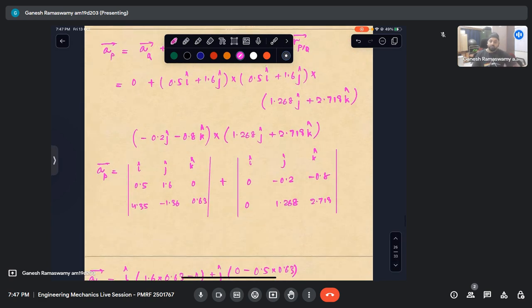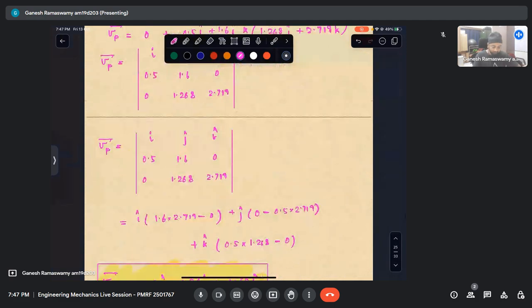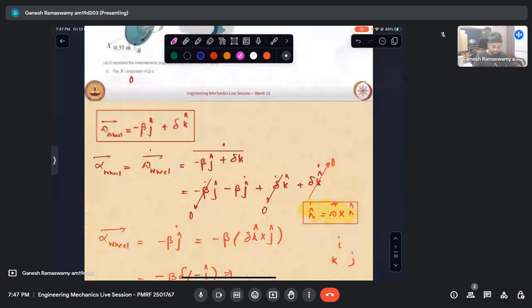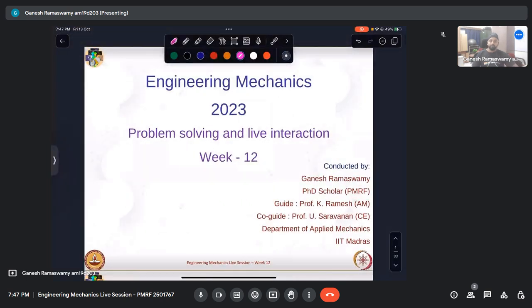So essentially what we have been seeing in this session is that once we have three-dimensional vectors, cross products become a little involved, but our basic principles of relative motion, like applying RFR equations, the rotating frames of reference, VREL, AREL, and then 2 omega cross VREL, the correction for Coriolis component, all these essentially remain the same. What changes is that our vectors are now in three dimensions.